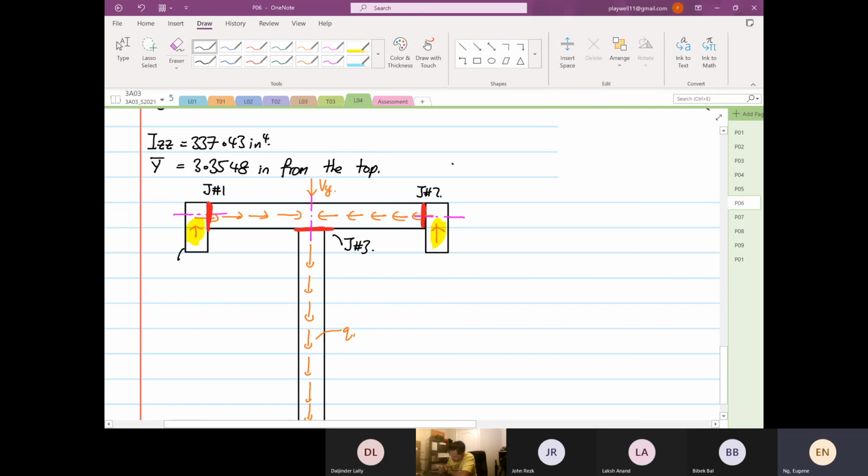I call this the minor web. These are the minor web. This center one is the major web. So why I'm saying this, with this, you are able to calculate the spacing. The area that you need to consider, the left web and the right web, are not connected, are they? They're independent. So the area we have to consider for the small web is just this area. It can be the left-hand side or the right-hand side.